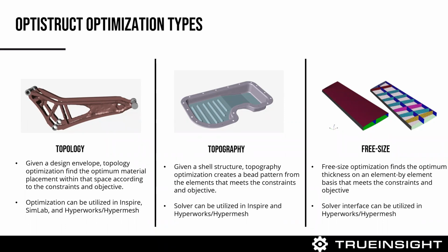Say we're setting up a basic linear static study with some restraints and material properties. Everything in that red magenta is where you're removing mass. Everything that's silver is known as the non-design space, whereas red is design space. The silver does not have any mass removed.